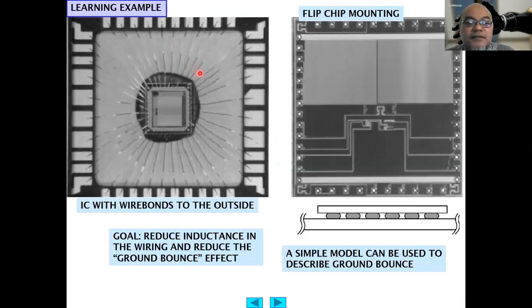So this is how it looks in an IC. If you open the packaging, the integrated circuit is actually in this part. The one that you see from the outside is usually only the electrical pad here. This is usually covered by black coverage. Okay, but the actual IC is very small here. Then it is wire bonded, so that this can be soldered to the PCB.